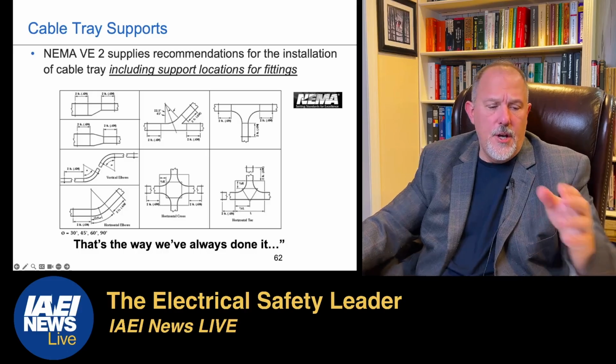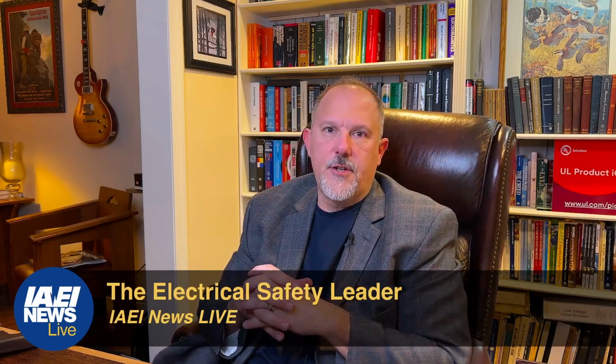I would argue that when you're dealing with cable tray, bonding is obviously a very important detail that's probably missed often. But I would argue that the supports are probably your second area of major concern in the application of cable tray. Think about the materials that you're using as well. Make sure that the application has the right solution.